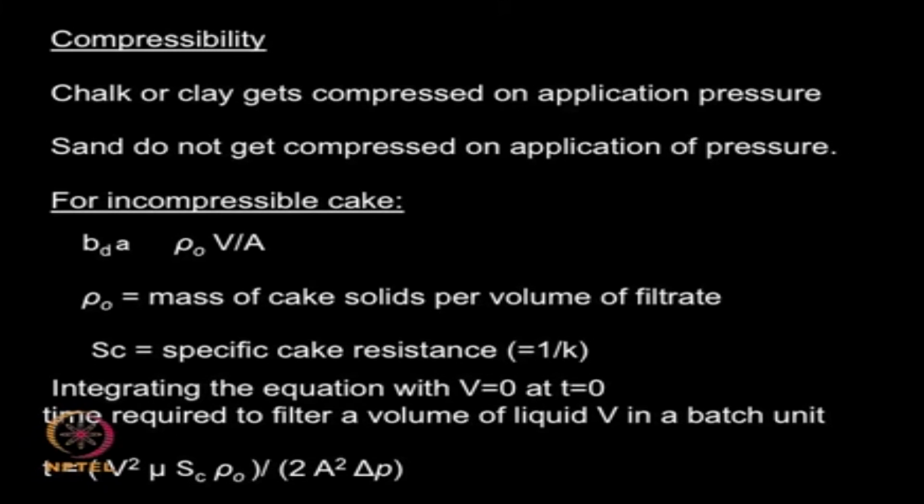sometimes the bed itself can offer resistance if we increase the pressure of the filtration process. If the bed resistance increases as we keep on applying an external pressure, then it is called a compressible solid. That means as we keep increasing the pressure, the bed gets more compacted.